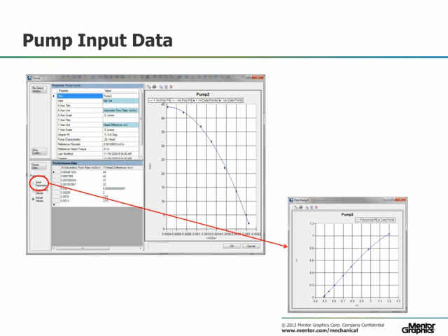This special feature will allow the user to input flow versus head data similar to that a manufacturer might normally supply or can be obtained from testing, then convert to a Suter parameter by simply adding a reference point for flow rate and head. Typically, this reference point will be associated with the rated conditions for the pump.